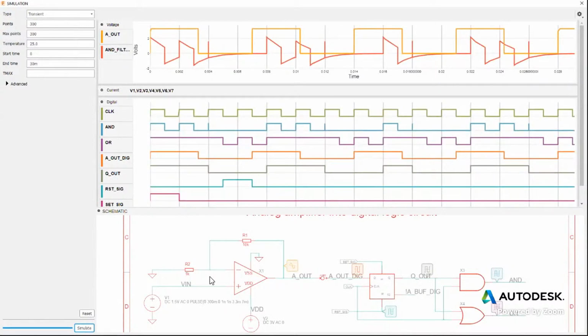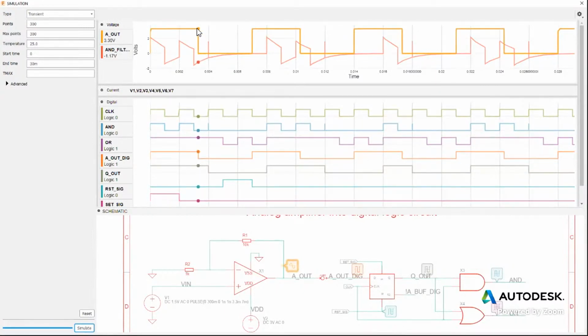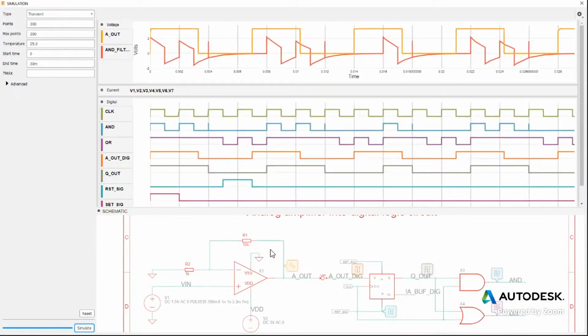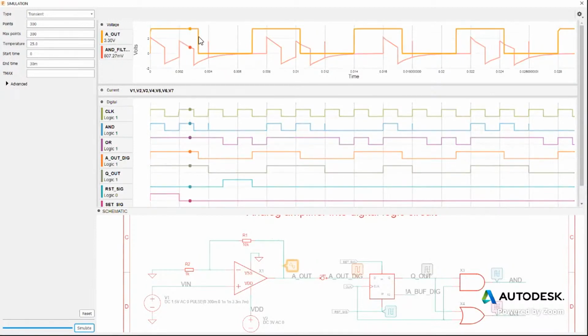The 1 nanos that are here is basically to indicate that the rise time is really, really fast, so it looks like a square, okay? So that looks good. So far, that's what we're expecting. It goes from 0 to 300 millivolts. It gets amplified by a factor of 10 over here, and that's what's expected. So that's good. That's promising.